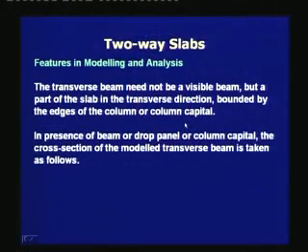The transverse beam need not be a visible beam, but a part of the slab in the transverse direction, bounded by the edges of column or column capital. In presence of beam or drop panel or column capital, the cross section of the modeled transverse beam is taken as follows.